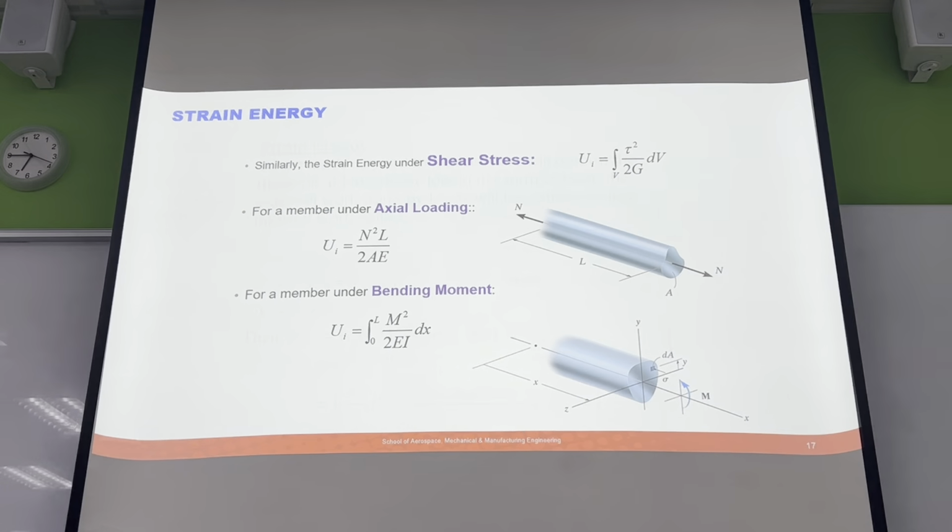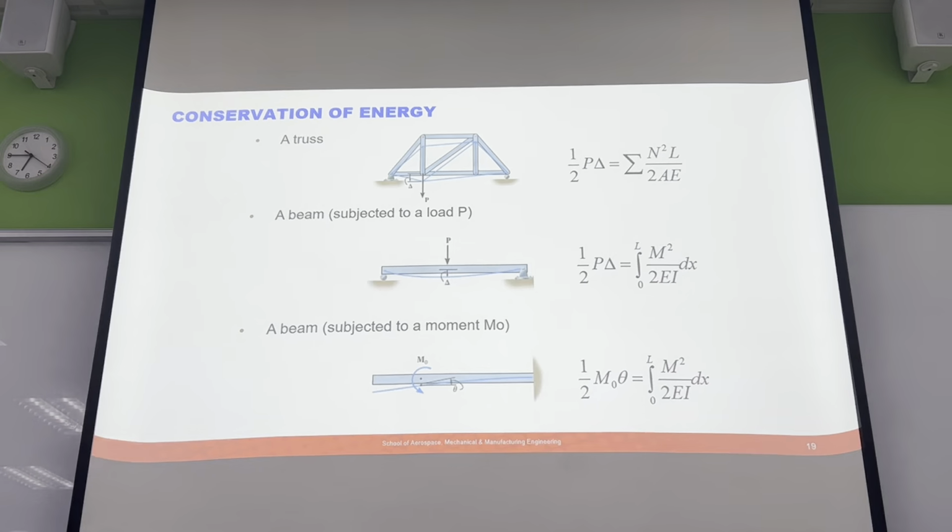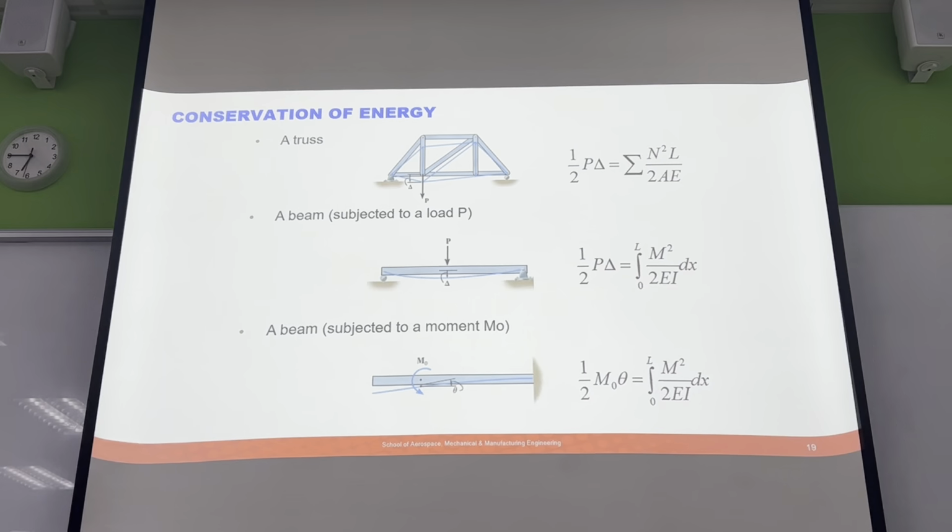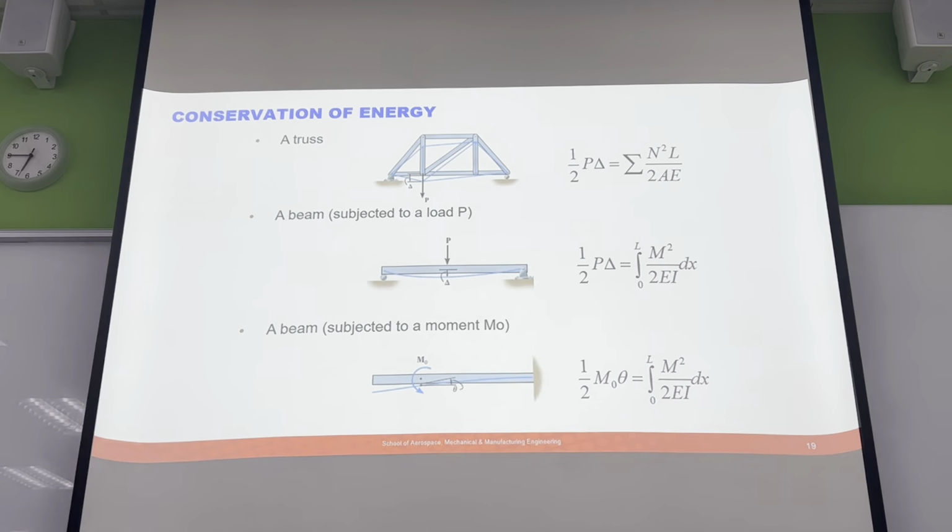And we can do that for a beam in bending. We have M and EI. And if we can get M as a function of x, it's pretty straightforward. So this is what we get here, this equation. That's where that comes from. And the reason why it's M squared is because that was stress squared.